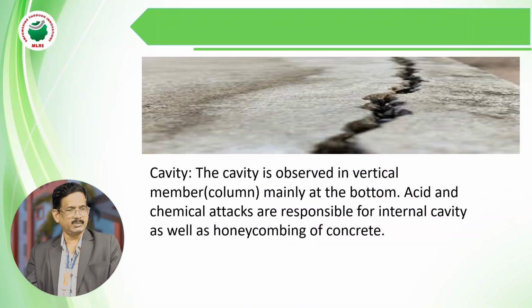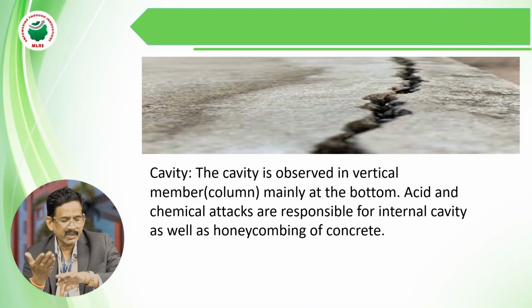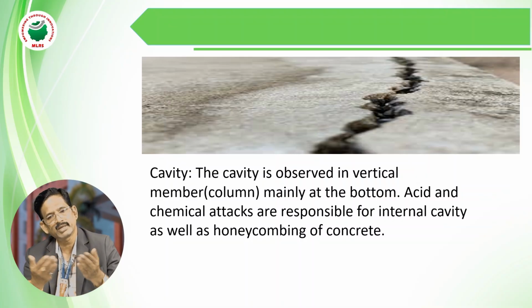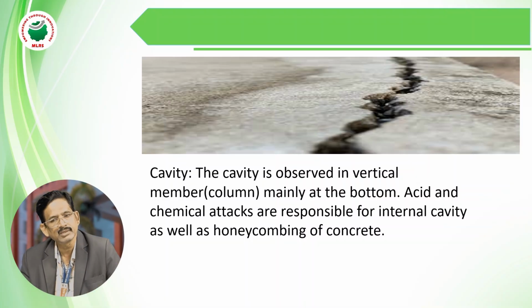Yesterday I had discussed it. Suppose instead of 12 mm, if the corrosion occurs, the 12 mm will be reduced to 10 mm, 10 mm will be reduced to 8 mm, 8 mm will be reduced to 6 mm, may or may not be, depending on the seriousness of the effectiveness of the corrosion of the steel reinforcement.